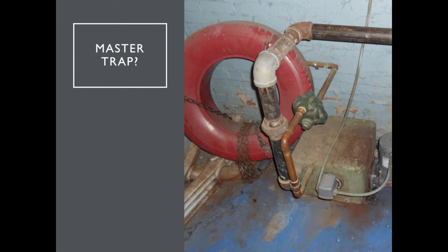Thank you, Ray. And Kevin is asking, what should you do if you see steam? Well, if you see steam, the first thing I would do is look to see if it's a leak. The second thing, if you see steam coming from the vents, is look on the boiler feed or the condensate tank to see what my steam pressure is.